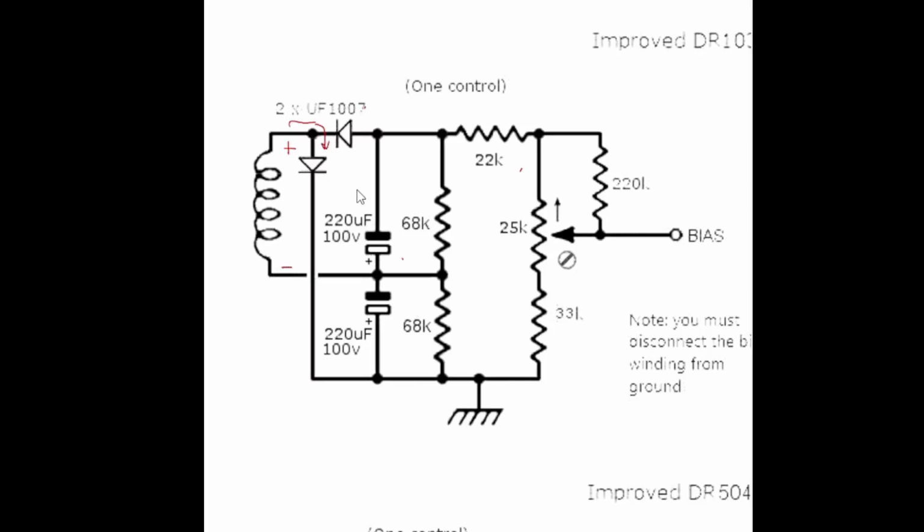Okay, so it's going to flow down through that diode. These points are not actually connected. This is a gap in the wiring. So it's going to come around here. And because this is the more positive side of this electrolytic capacitor, this capacitor is going to get charged up.